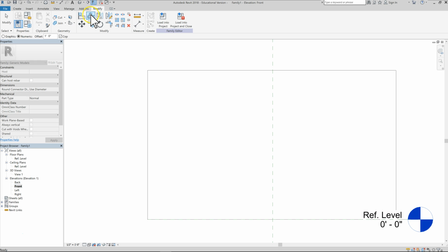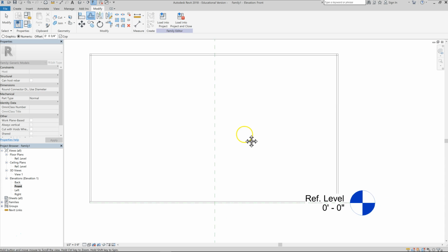I'm going to click on the offset button that looks like a thumb. I'm going to go to the offset window, and type 3/4, enter. Then I'm just going to go around and start offsetting to the inside. I'm going to offset the bottom here, and each side. Sometimes the computer can predict what you're trying to do, and it'll trim up some of your corners like this one right here, but it didn't get all of them, so we'll have to correct some of those corners.